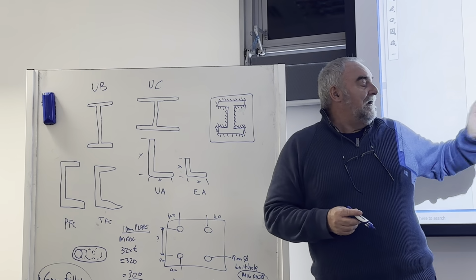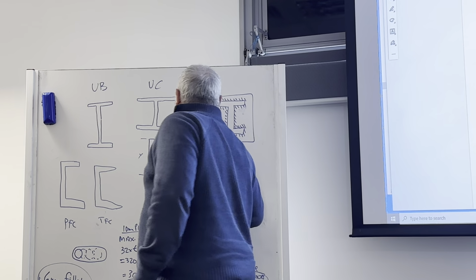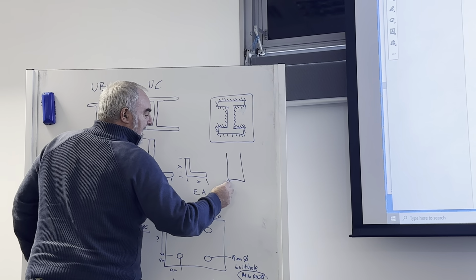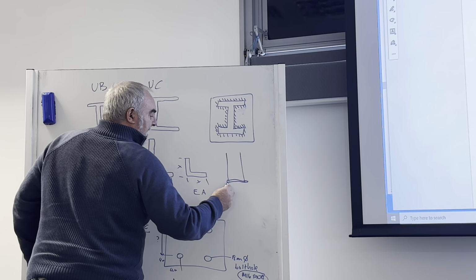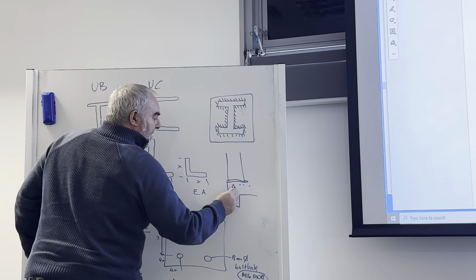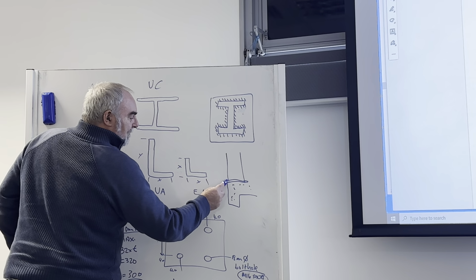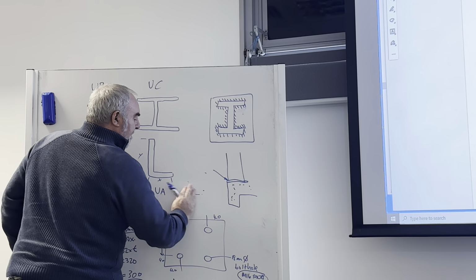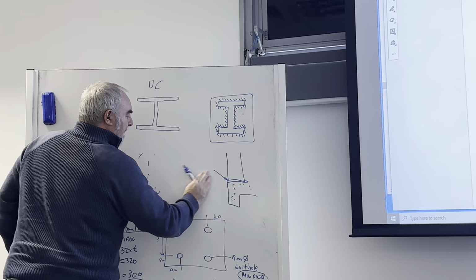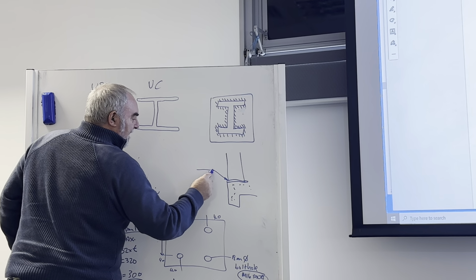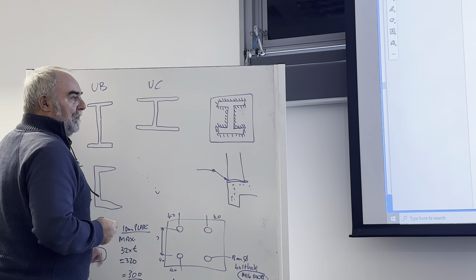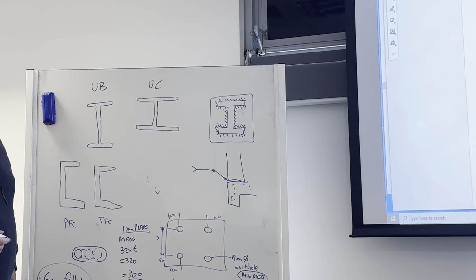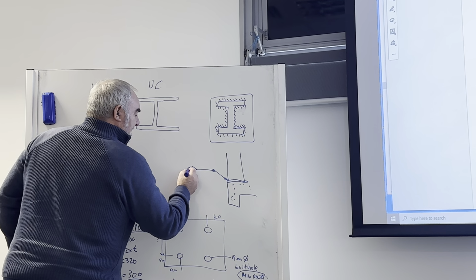The arrow connecting? Right, so the weld symbol is when you look at your elevation, and here's your plate, and here's your side of your concrete, right? And you will have the arrow going to it. And it'll come along like that. It'll have a circle on it, meaning an all-round weld. It'll have these beaks at the back like that. It'll have 6 on it.